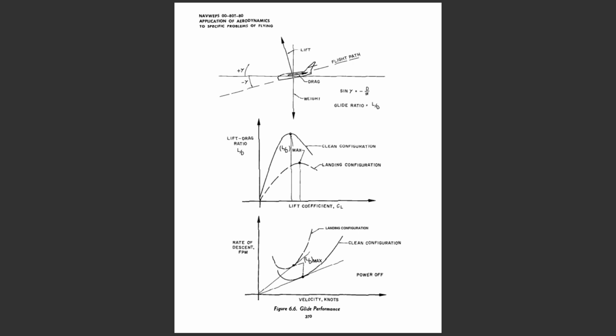If the airplane angle of attack is increased above the value for L/D max, a transient reduction in rate of descent will take place, but this process must be reserved for the landing phase. Eventually, the steady-state conditions would be achieved, and the increased angle of attack would incur a lower airspeed and a reduction in L/D and glide ratio. The effect of gross weight on glide performance may be difficult to appreciate.